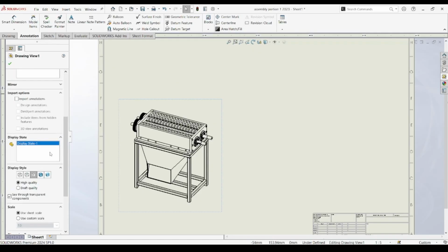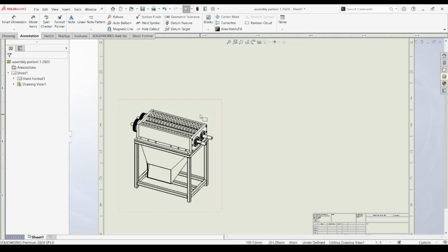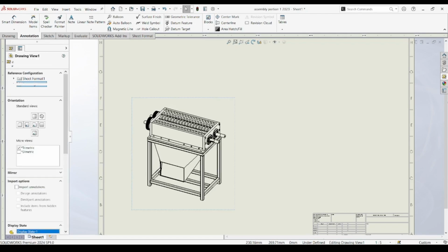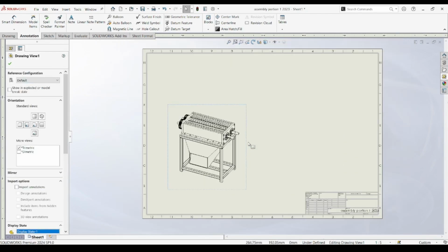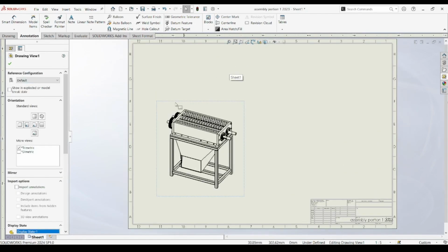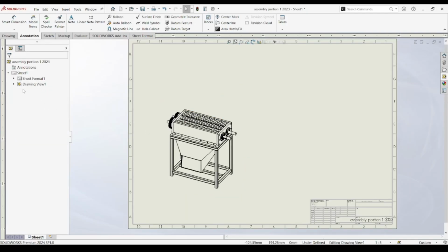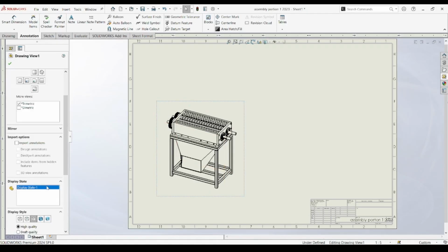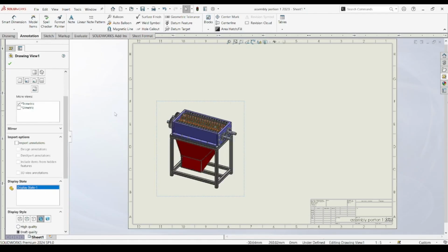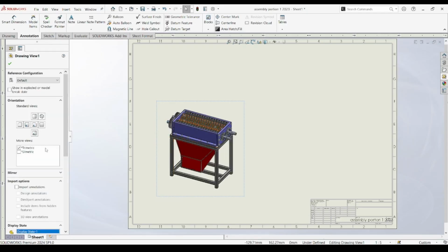It requires customization. So, we dive into editing the column headers, adding or adjusting fields like part number, description, quantity, material, and possibly weight or supplier if needed. For example, instead of a vague Part 1 or Part 3, we ensure every item has a functional, readable name, like rotating blade 8 hole or spacer 5 millimeters.